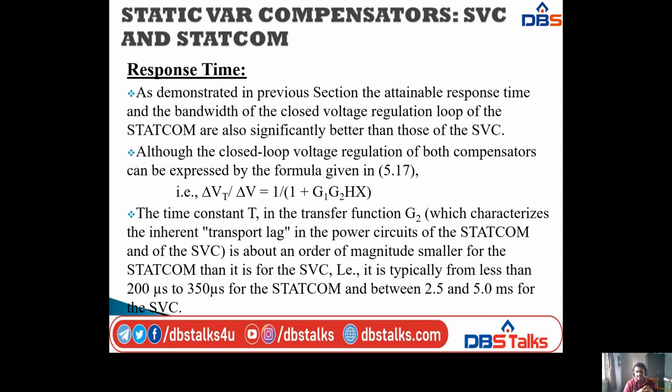Here the time constant T in the transfer function G2 is about an order of magnitude smaller for the STATCOM than for the SVC. It is typically from less than 200 microseconds to 350 microseconds for the STATCOM and 2.5 to 5 milliseconds for the SVC.